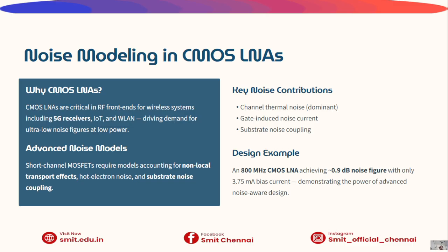The dominant noise source is usually channel thermal noise. Additional contributions come from gate-induced noise current and substrate noise coupling. Advanced noise models help engineers predict amplifier performance and optimize transistor sizing, bias conditions, and matching networks.